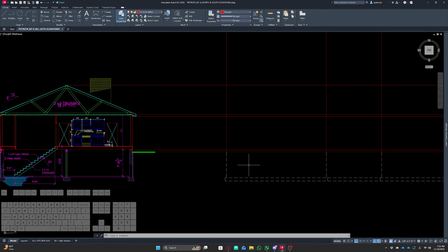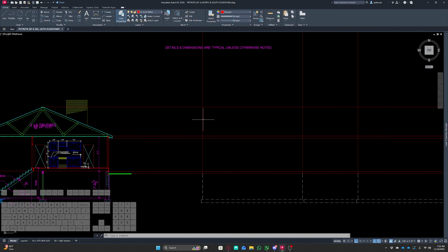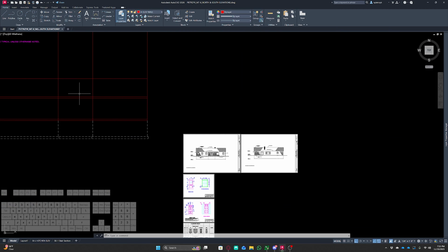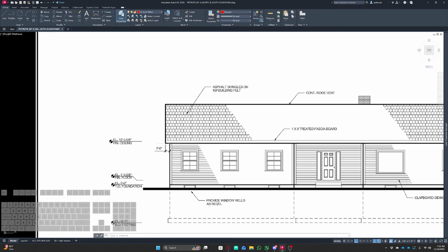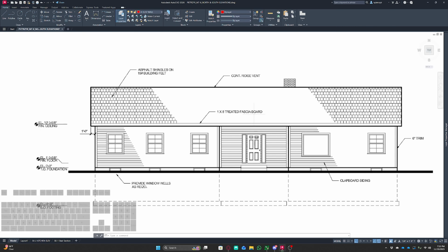And when I say major massing, I mean things that I need to change on the outside of the building. So the next thing I need to do in order to get this kind of offset here, because honestly this shape is very simplistic, is bring out my roof plane by a foot.